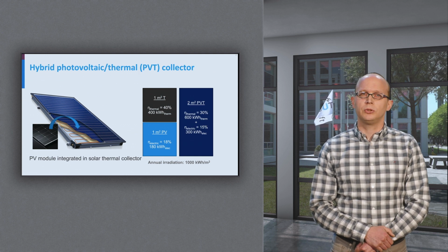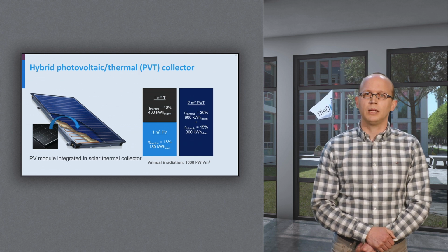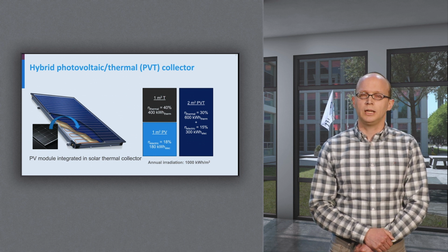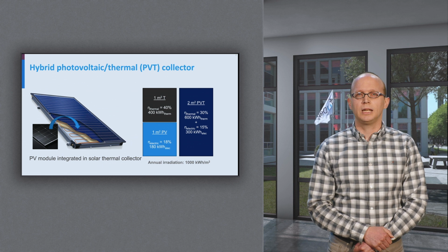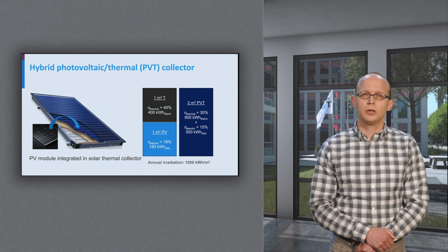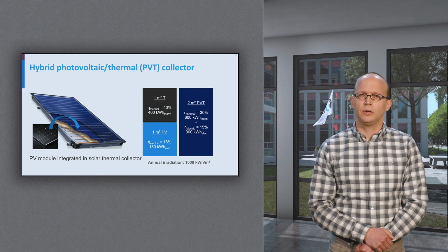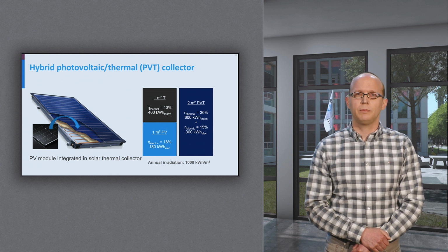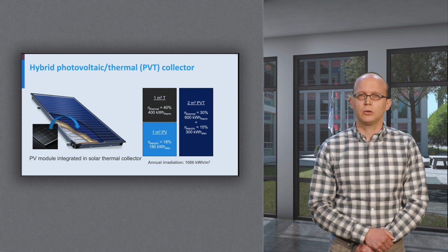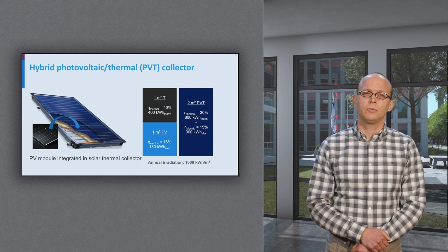Finally, I'd like to introduce the PVT hybrid collector that integrates photovoltaic module and the solar thermal collector into one device that generates electricity and heat simultaneously. Because of additional losses, the electrical and thermal efficiency of this PVT collector are usually a bit lower than the electrical and thermal efficiencies of the PV module and the solar thermal collector respectively.